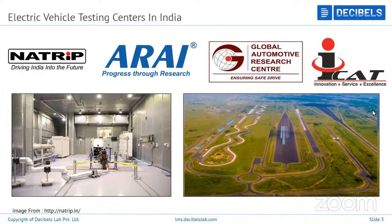So as I was mentioning about the vehicle testing standards which are followed, these are all controlled environments, where you can see on the left hand side there's a dynamometer. The resistive forces are simulated via a fan, and all the loads are sometimes again simulated via the dynamometer, certain loads which are not completely realistic to what you drive in day-to-day life, right? These standards give you different results when you compare to real.